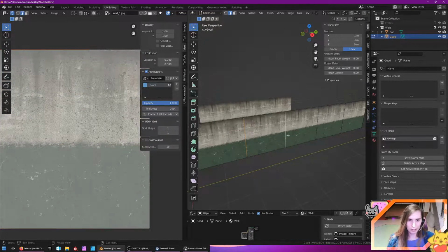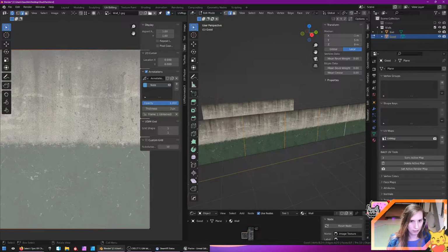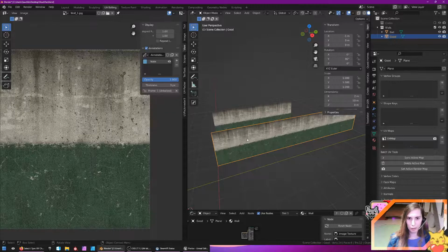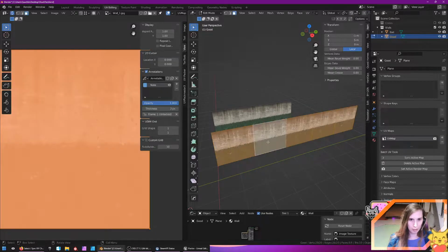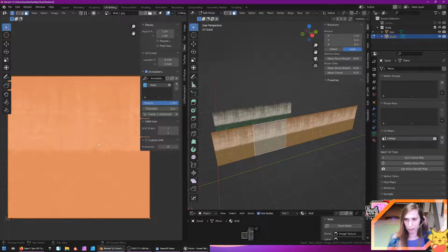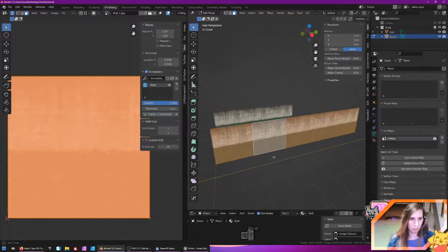The downside is that you're going to have more faces, but in my experience, it's way better to have good looking textures than a few more faces. Since Unreal will create the light map UV from your UV map, it will result in some problems when you stack UV maps, and you get overlappings when baking.